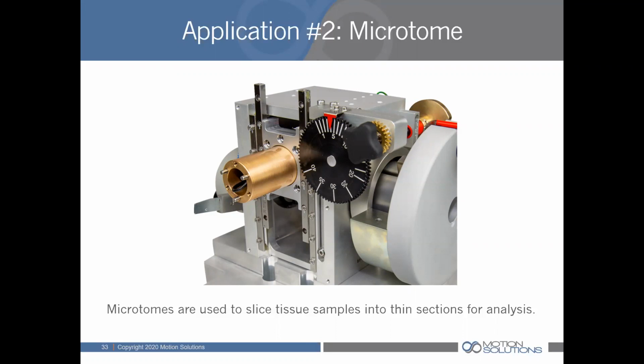In the extending or y-axis, because we're making such small movements, we're only moving between 1 and 40 microns with each slice, we actually can use a plain bearing here. We don't need rolling elements supporting the load. The friction is minimal because of such small movement.